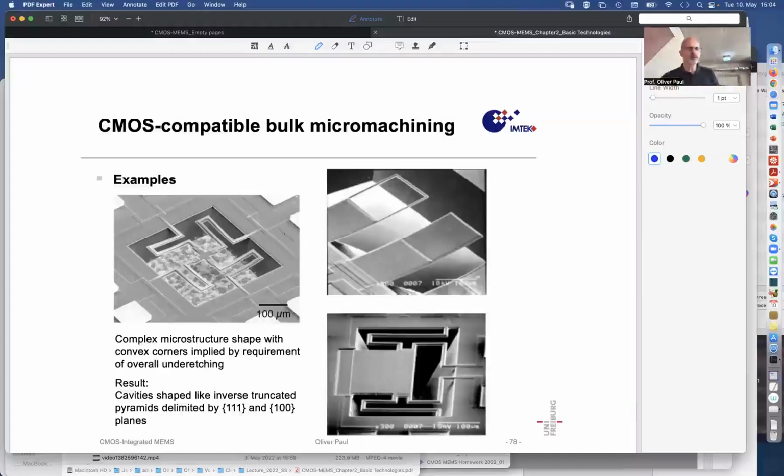The structure on the left is kind of complicated. It's a cross with 4 arms that allow again to heat a resistor at each of the 4 arms, and then also to measure at the same time the temperature of those ends of the 4 arms. And such cross-shaped structures are well known in materials testing, in electrical materials measurements, as Van der Pauw test structure.